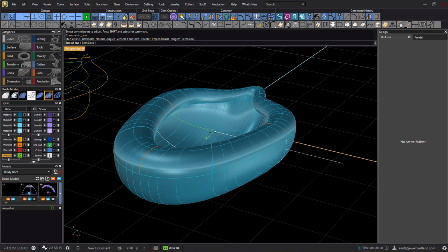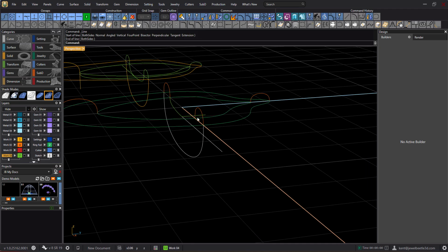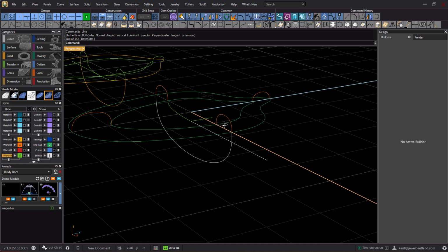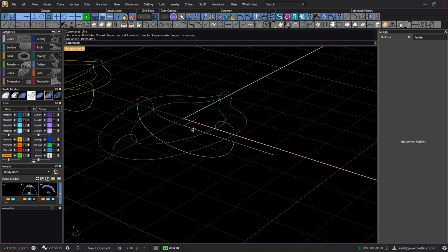And if I don't have planar on, when I make my tick, it doesn't matter which way I go. I'm going to go that way. Then if I didn't have planar on, this next click would have been up higher, okay? This button maintained the plane that I first clicked on, okay? All right, there's probably another lesson in planar there somewhere.